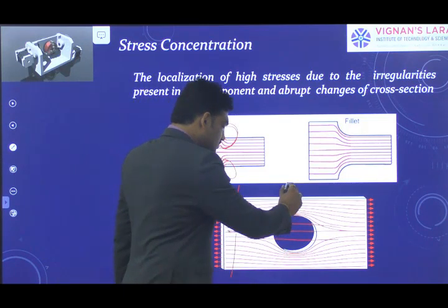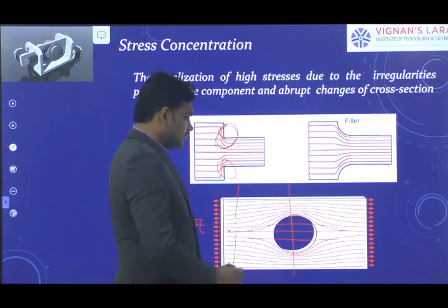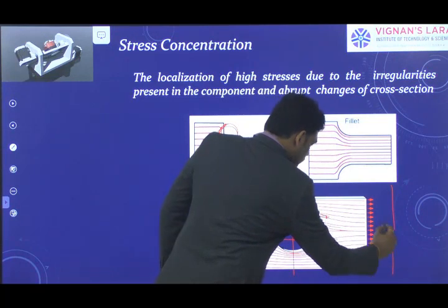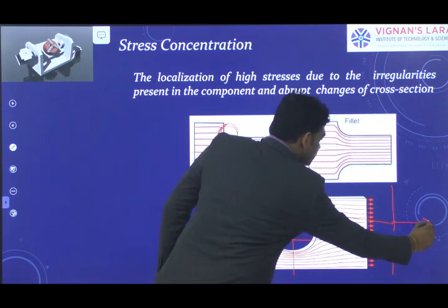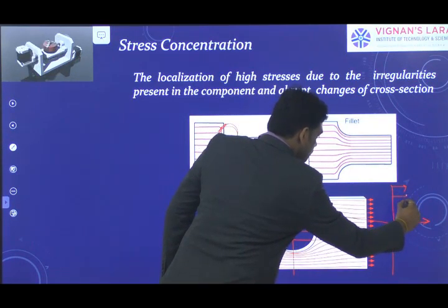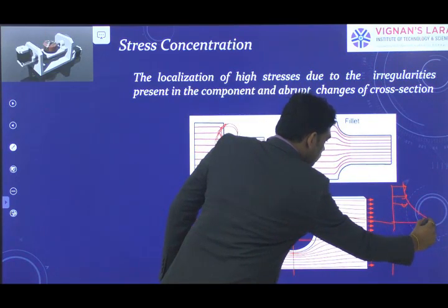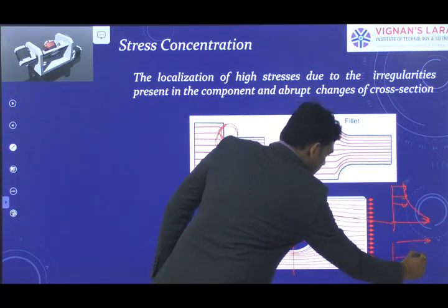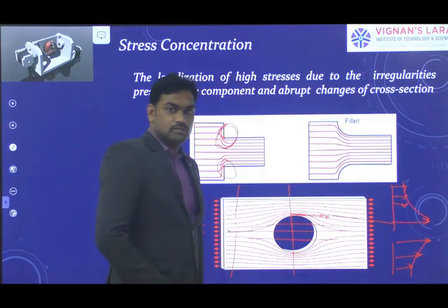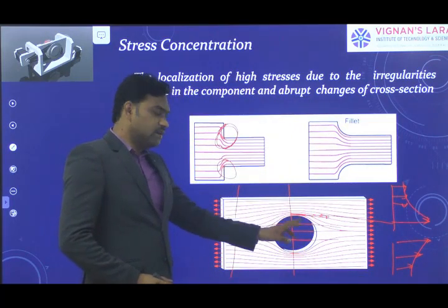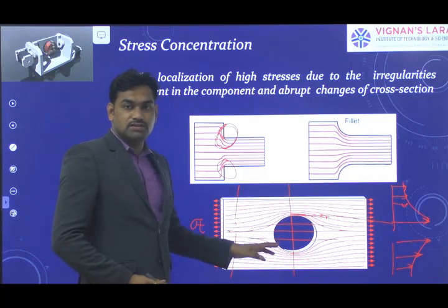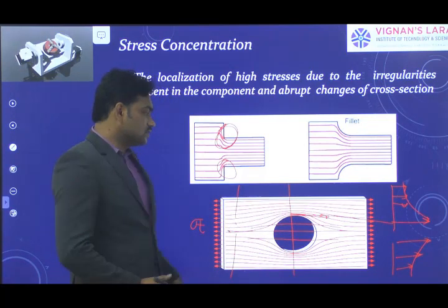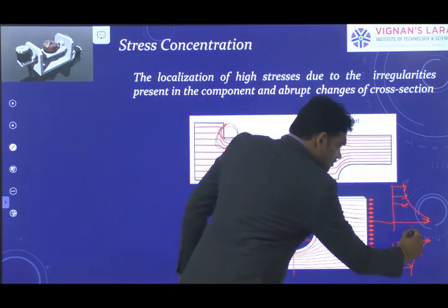But at this particular section near the hole, the stress induced is very high. Whenever there is a geometric obstruction, a sudden change in geometry produces a greater stress.